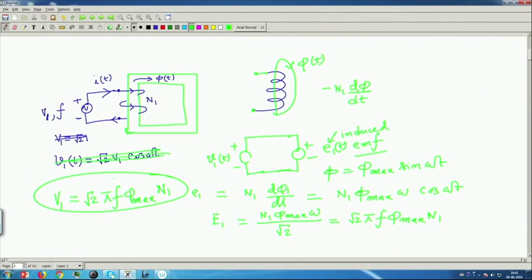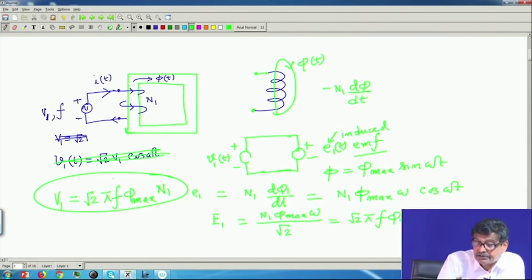So, what I have told you is that in case of AC, it is the same magnetic circuit which I considered with DC excitation. If you connect it to an external voltage source which is alternating in nature, sinusoidally, and the RMS value of that applied voltage is known, the current whatever flows has to be sinusoidal. Therefore, phi created inside the core of this magnetic material too will be time dependent and vary sinusoidally.